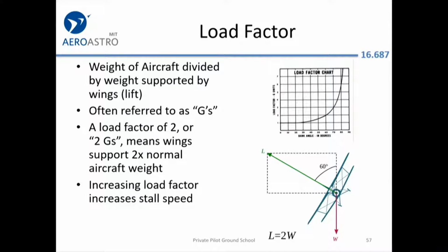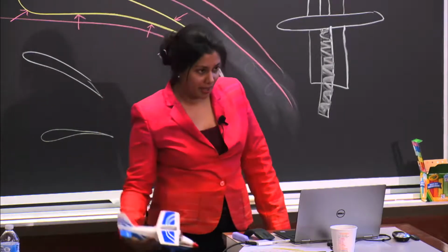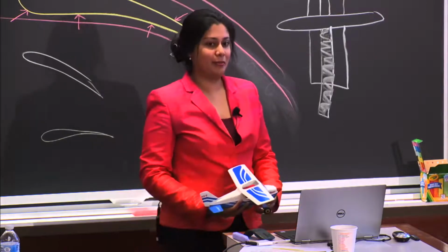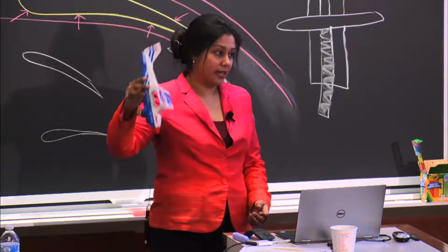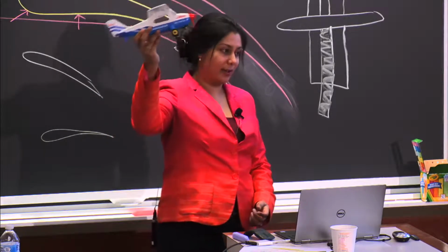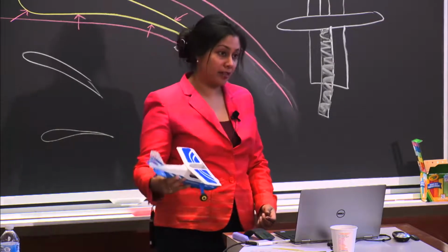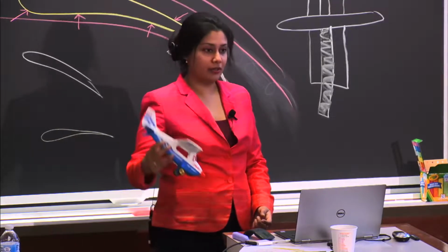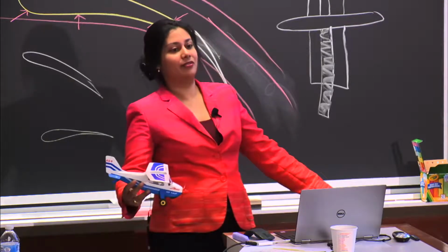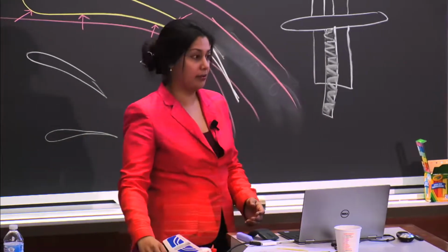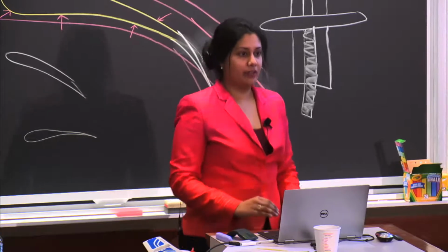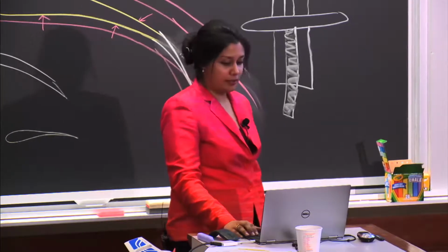But another thing to think about, back when we were talking about that zero gravity flight and a plane flying in a parabolic trajectory, or a roller coaster: when you're at the bottom of the roller coaster, you really feel like you're being pressed down into your seat. In fact, when we were on that zero gravity flight, although at the top we had 30 seconds of weightlessness so we could do our experiments, when you go to the bottom of the parabola, you basically get 2g, or twice what you normally feel, and so you have to kind of lay down and let that happen before you come up again. And so when you think about load factor, just think about you being at the bottom of your roller coaster and really feeling kind of twice that force on you.